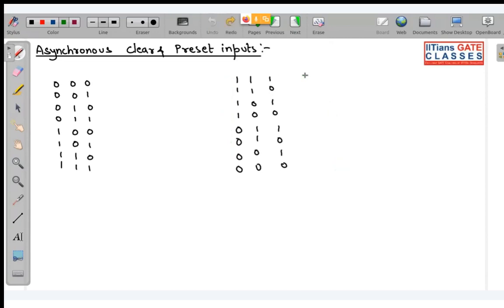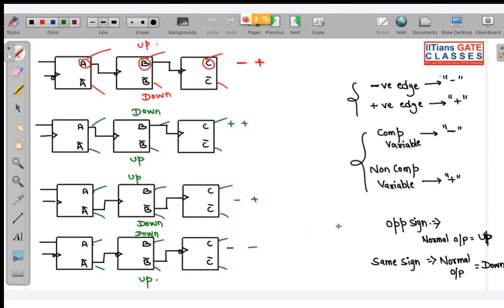But what if I want my count to look like this, if it is 3-bit: 0 to 1, then to 2, then to 3, then to 4, then to 5, then back to 0. I don't want 6 and 7 in my counting states. These should be unused states. So what can we do? Note it quickly.